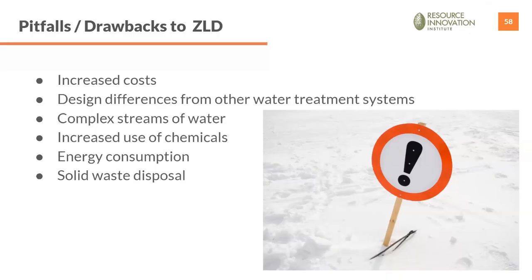The biggest consumption of energy in a ZLD system by far is by the evaporation system. So literally the amount of runoff recovery directly affects the cost to evaporate water. Our conversation with clients and CEA facilities is always around, what is your runoff percentage? Because a 10% runoff versus a 20% runoff is literally double your energy cost. It's really that simple. The way these systems work, they're very, very energy intensive.